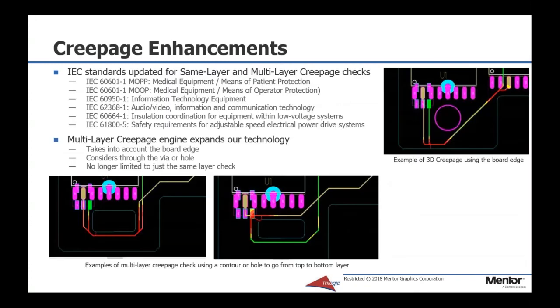We have 2 versions of the rule. Similar to the bare-bones creepage distance check, considering the multi-layer outer layers of the board will check automatically for high voltage objects that have the ability to affect or radiate energy to what we call a victim object or victim net. In the second version of the rule, following the same idea with the 2D same layer rules, we also have incorporated creepage distance checks, but have embedded the IEC standards into the rule.